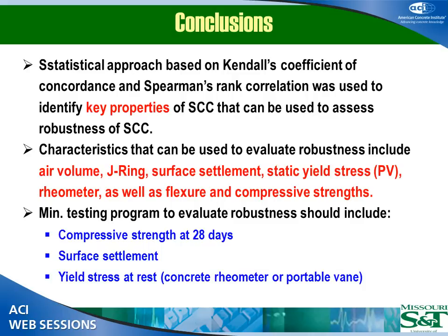Yeah, if you look at the coefficient of variation, for example, on any rheological property, they were very, very sensitive. Again, we are dealing with concrete that goes from a water-cement ratio point of view from 0.35 to 0.39. So your fresh properties would be very affected. In some cases, for example, you are not getting self-consolidation. You might get blockage in the J-ring. In other cases, on the extreme side, you might get bleeding and segregation. But in terms of mechanical properties, because the window is so small, when you are measuring your 7, 28, 56-day mechanical properties, the variations were not that high.